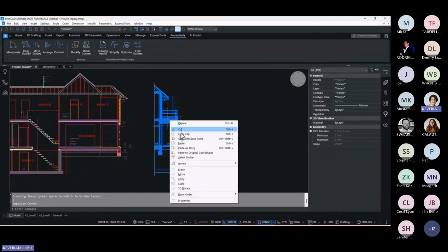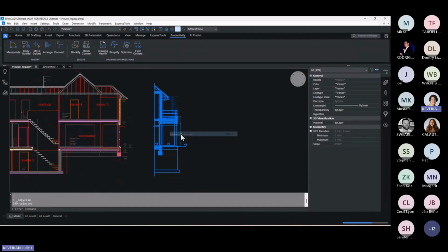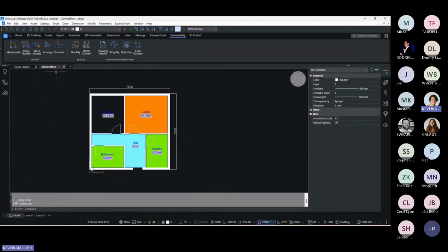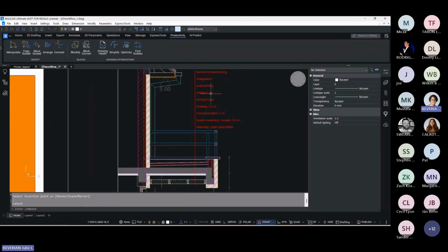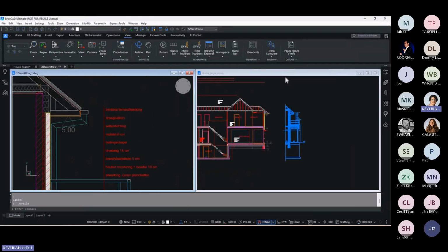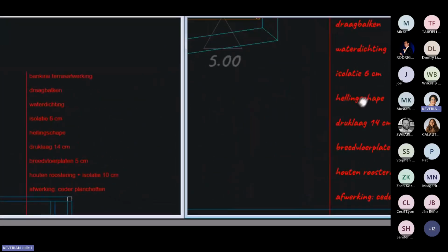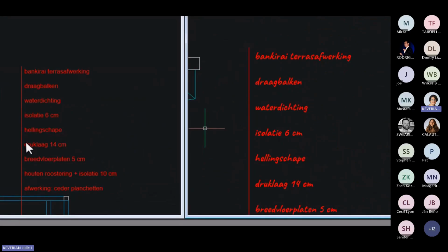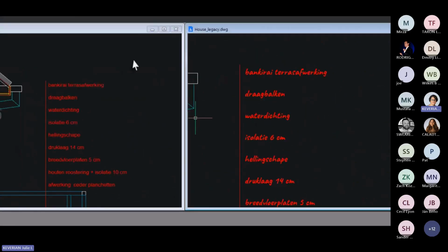Now, if someone changes that to a different font as seen here, it can cause issues when you copy geometry between drawings. Even though both drawings have a quote standard text style, they may be defined differently. The result? Unexpected changes in appearance of the text. The standard style in one drawing uses the Arial default font, the other one does not.